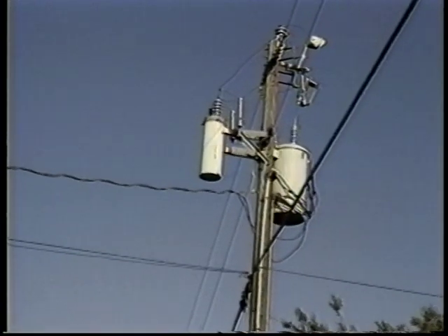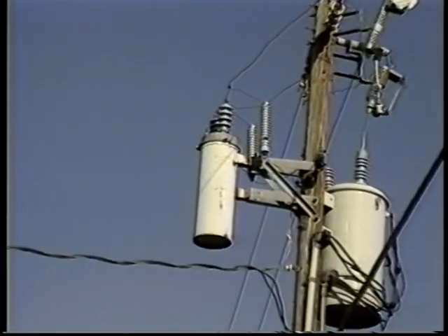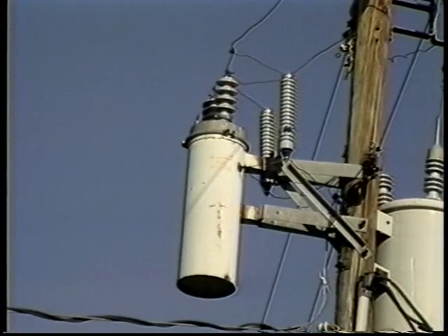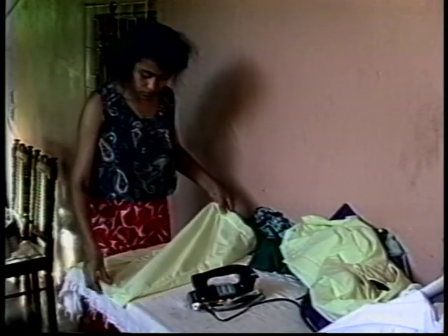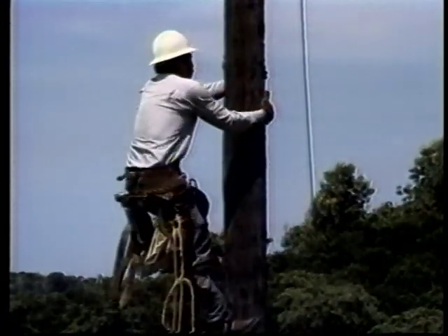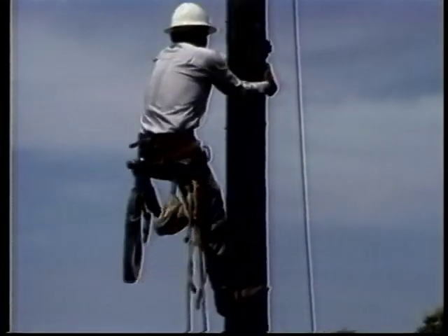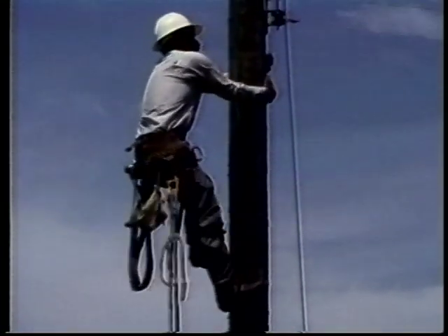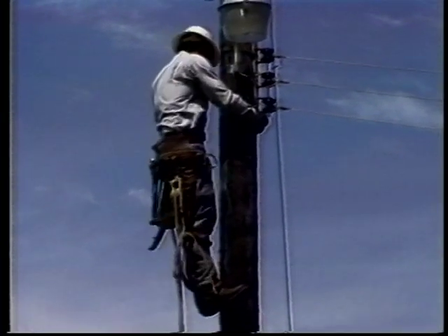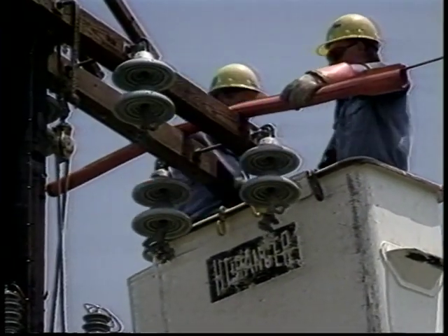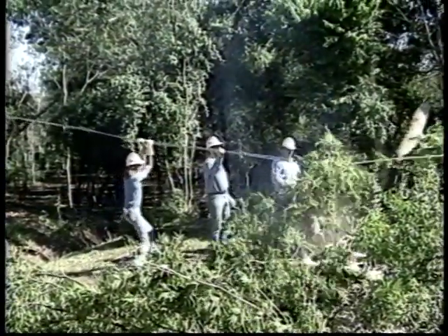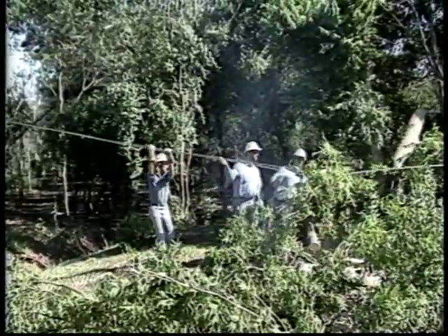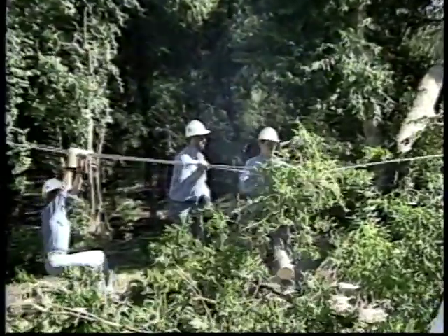In summary, the objectives of incorporating OCRs into distribution system sectionalizing are: to attain the minimum practical minute outage per consumer per year, to attain the minimum practical expense of service restoration after outages which are caused by primary line faults, to minimize damage to primary lines and apparatus during faults, to minimize the probability of a hazardous voltage at ground level or on grounded objects interconnected with the system neutral.